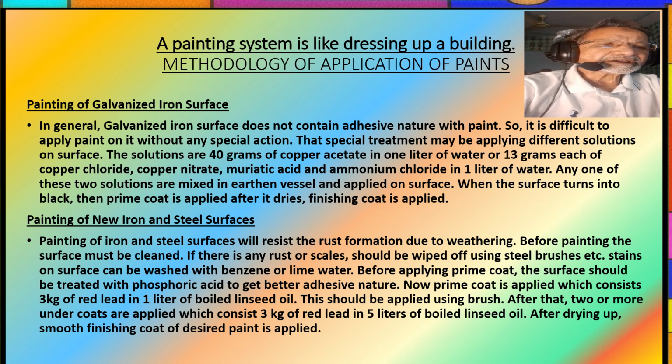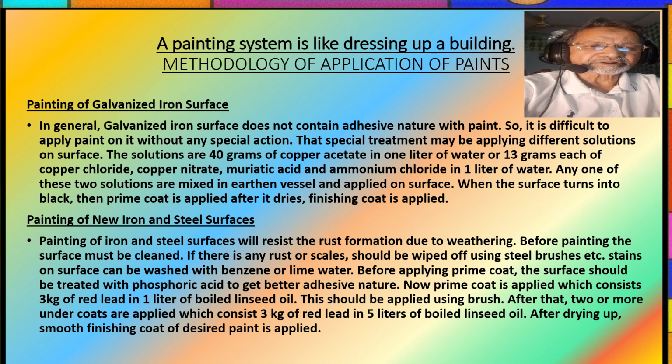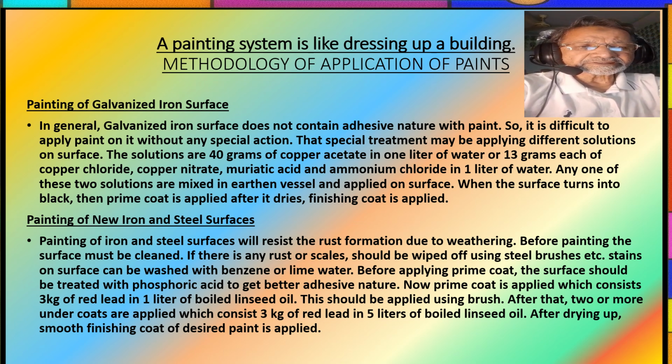Apply a galvanized metal primer that helps bind paint to zinc. Application: use a brush, roller or preferably spray for even application on metallic surfaces. Drying: allow the primer to dry fully, which typically takes several hours.